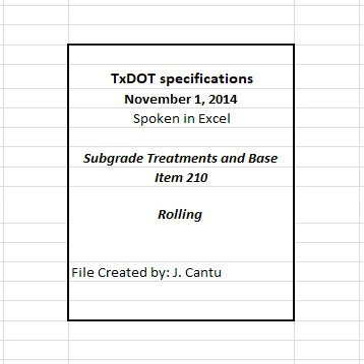2.5 Grid rollers. Furnish rollers that have 2 cylindrical cages with a minimum diameter of 66 inches and a minimum width of 32 inches. Mount cages in a rigid frame with weight boxes. Use a cage surface of cast or welded steel fabric grid with bars 1.5 inches wide, spaced on 5 inches centers in each direction, that undulate approximately 1 inch between the high and low points.